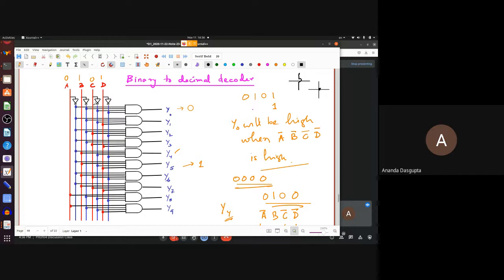And for analogs, the rule is unless otherwise stated, if two wires cross like this, they're actually connected. If you want to show that they are not connected, you draw a bump either on the vertical wire or on the horizontal wire. It doesn't matter which one. But this bump signifies that the wires are crossing without actually touching each other. Okay.